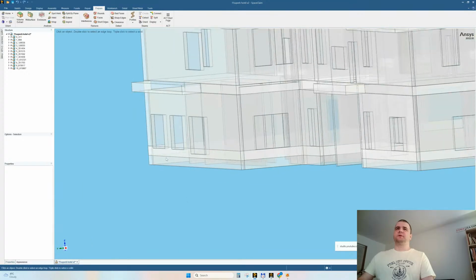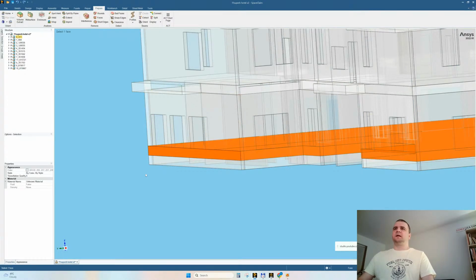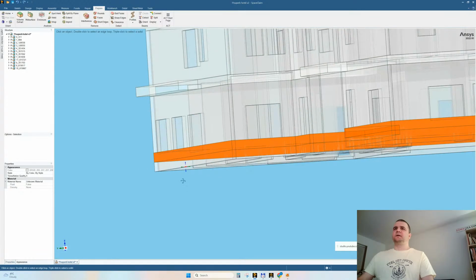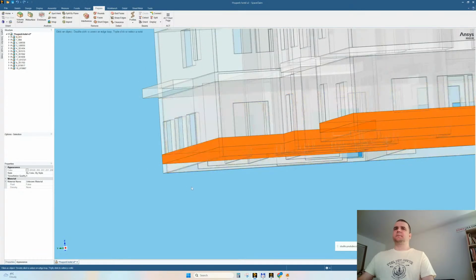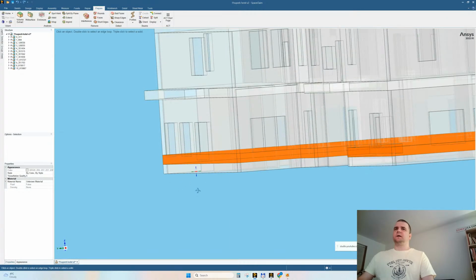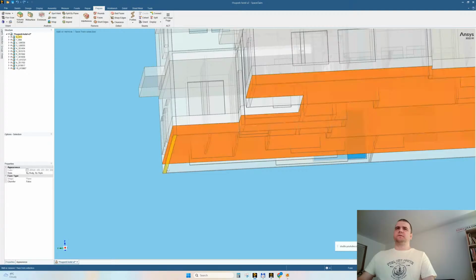For example, look here. This is something extra, yes? With Control and middle mouse, we can hover between geometries that overlap. Yes, we can hover between them. Let's triple click here, and we can see that there is a floor. And this floor, sincerely, because there is no floor downwards here, I would like to move it downwards. Just out of curiosity, let's see the distance, 500 millimeters.